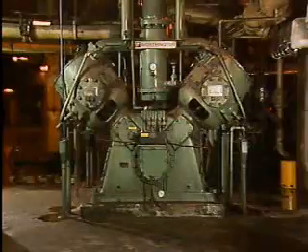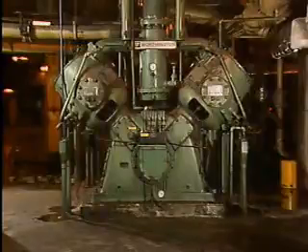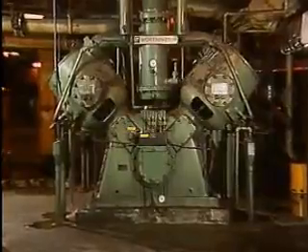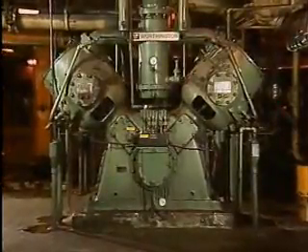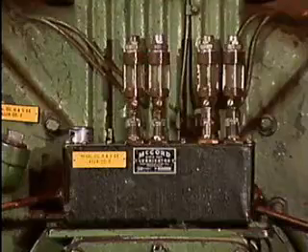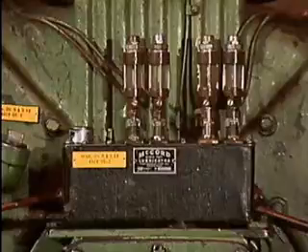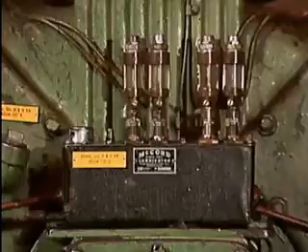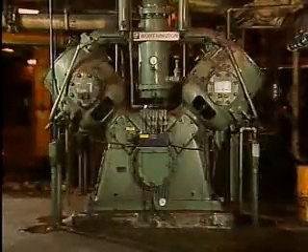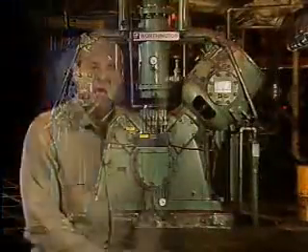Another important job that must be performed for a compressor is cooling. When a gas is compressed, heat is produced. This heat can cause two major problems. First, most compressors are oil lubricated, and excess heat can break down oil, causing it to lose its lubricating characteristics. If this occurs, the compressor's internal components can be severely damaged. Gases expand when they're heated, and since a compressor is designed to compress gases, this effect creates an additional force that the compressor must overcome.